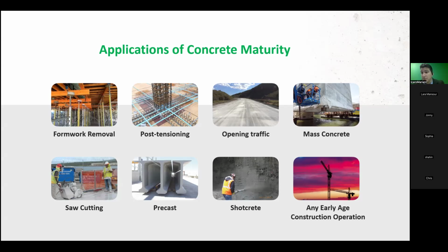Yes, and more than that, Hugh. When you create what we call a maturity calibration, because for the sensors to work, you need to calibrate the mix design. What happens is you create the maturity calibration by casting samples, breaking them, and actually measuring the strength. So when we create this, we can actually feed the system with the mix proportions. So let's say you have 500 pounds of cement type 1, 200 pounds of fly ash type C, whatever. You can actually pinpoint all your mix proportions.